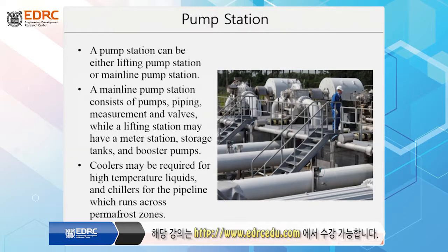I was involved in the Norman Wells oil pipeline in the Arctic. When crude oil is being transported, flowing, heat is generated because of friction heating, the Joule-Thomson effect and all those kinds of things. So the surrounding pipe is getting hotter, several degrees higher. If the surrounding soil is frozen, what will happen? The pipe could buckle. To avoid that, you have to chill the crude oil, let's say to minus 5 degrees C. That way, after transporting a couple of 100 kilometers, it still couldn't melt the surrounding soil. That's why there is a chiller.